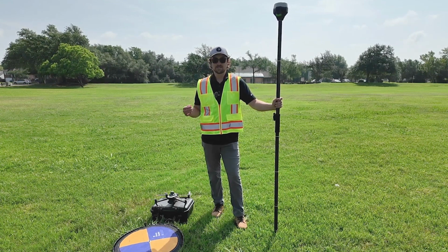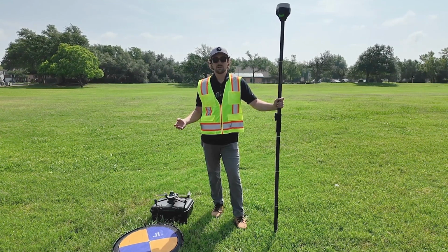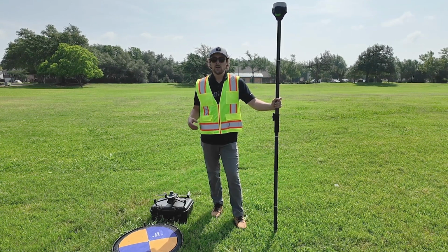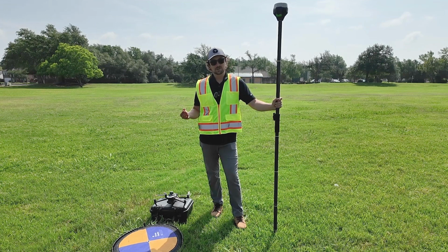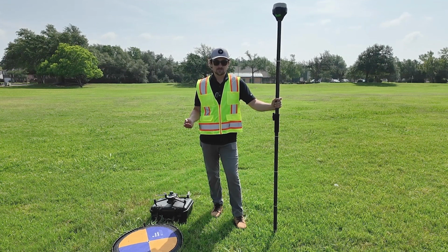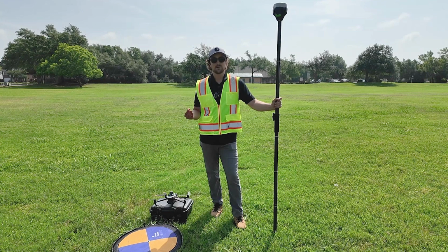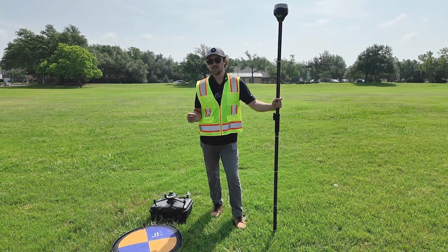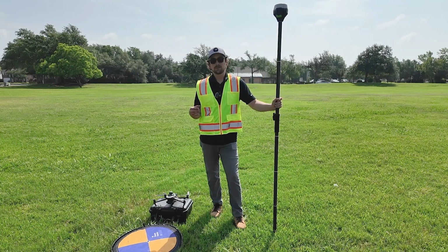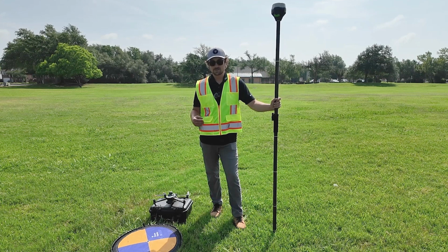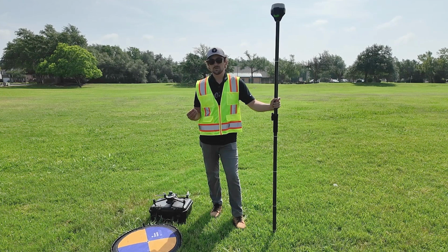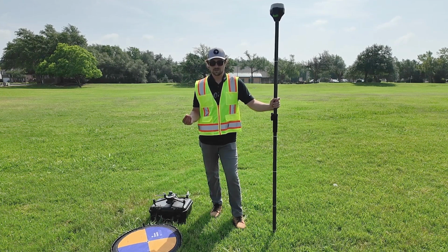Some things we're going to be talking about today are some considerations when flying a high accuracy mission. So this site is 33 acres. We decided, because it's a relatively small site, that we're going to go with a single GCP workflow. If your consideration, even with small sites, is that you really need a high level of accuracy, you can do a full GCP map with all those GCPs encompassing that whole map. But for today's purposes, we're going to do a single GCP workflow where we can still get really good results for a 33 acre site like this.